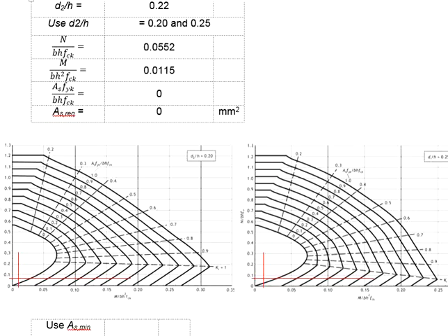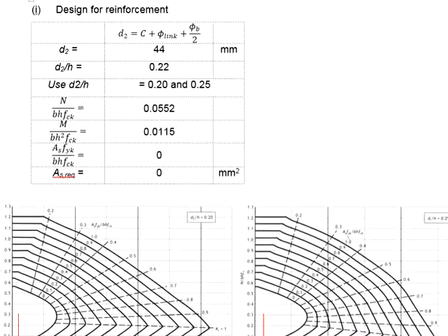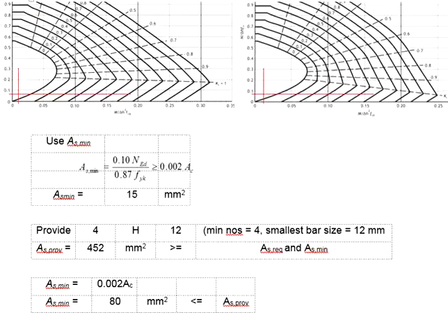You do interpolations, you know that no reinforcement bar shall be required. However, in the design of reinforced concrete structure, we cannot simply put the entire column purely concrete without any reinforcement. When we calculated the reinforcement bar is not required, that means the amount of reinforcement bar shall be governed by the minimum As. Therefore, our next step is to calculate the minimum As.